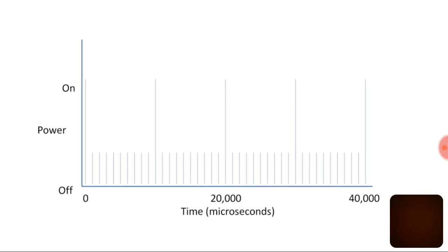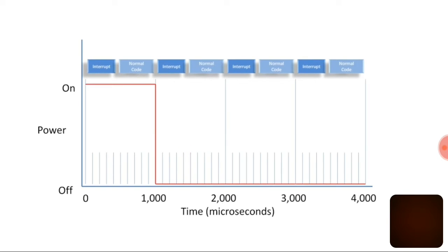The higher our PWM resolution is, the more levels of brightness we can display. However, since the duty cycle is fixed at 50 Hz, more resolution requires finer timing from the microcontroller. The faster the microcontroller, the smaller durations it can time. Another limiting factor is the code execution. The microcontroller must not only time the interrupt which causes the pulse generation, but also run the code which controls the LED output, which must complete before the next interrupt is called.